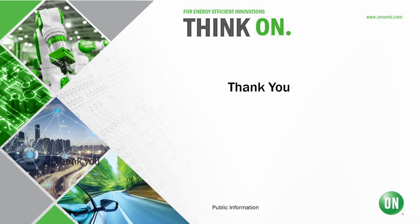Well, it's a series of still captures. So we offer very high frame rates. 60 frames per second is common for the automotive ADAS and AD space. So then a series of still images goes into the core processor, the autonomous driving processor, and it then, studying those series of images, will determine if, for example, that pedestrian is stationary, moving in the path, or outside the path.